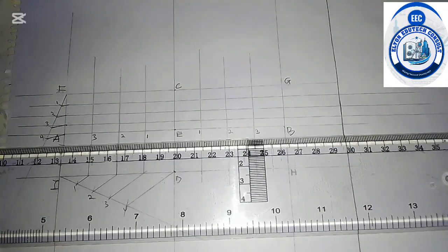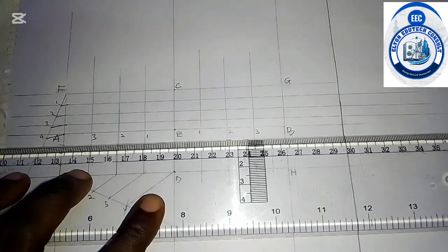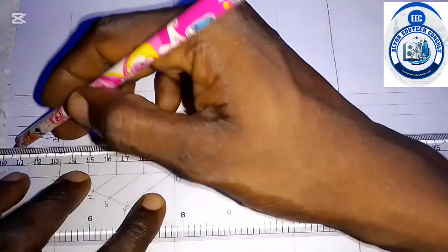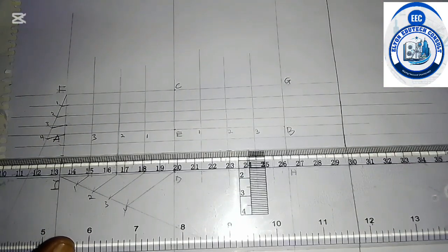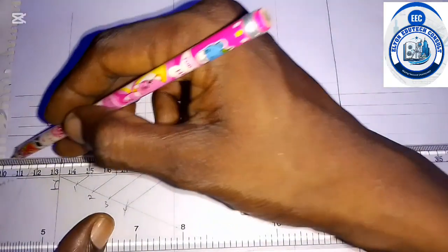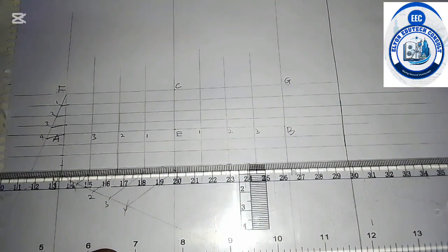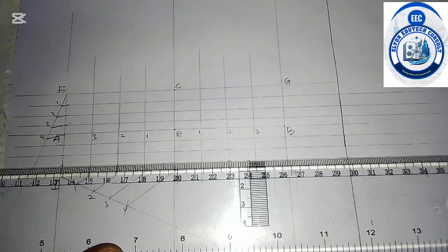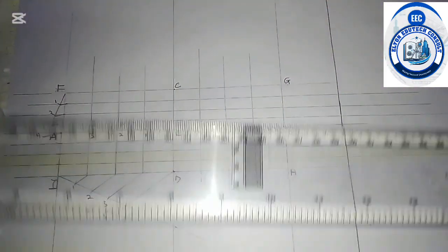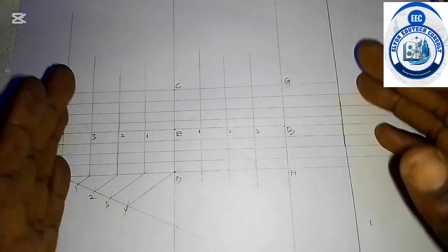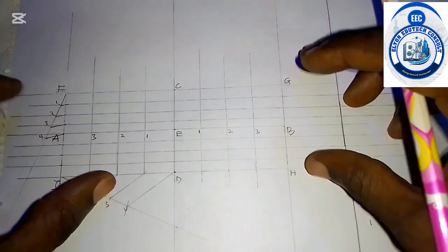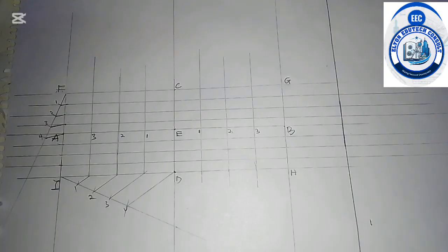All right, so draw this. Please, everything should be thin line, okay, especially when you are using this rectangular method, so that your ellipse is going to be visible and it should be different from all the projection lines. So that's what we have here now. So we have neatly divided our rectangle in the appropriate way we should.